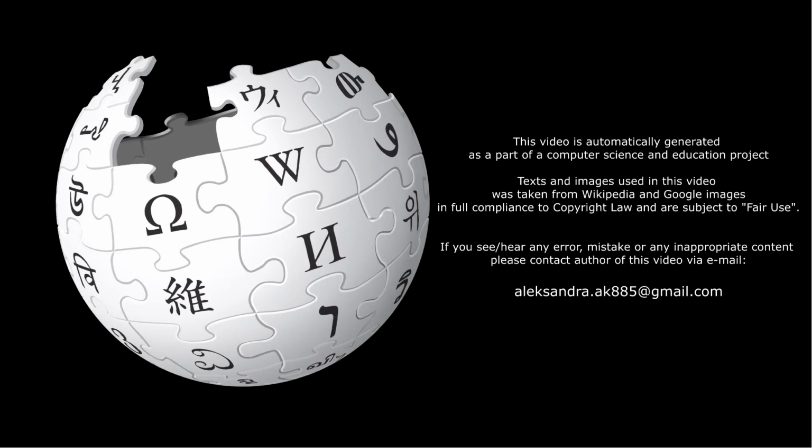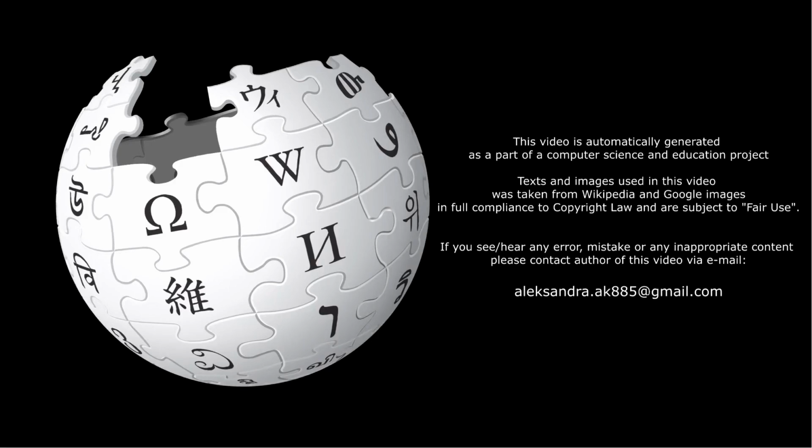Still, since diffusion of contaminants is expected to be much slower in water than in air or vacuum, consideration of optics contamination actually favors immersion lithography. Water-soaked photoresist also has been demonstrated to produce very satisfactory images. In addition, 193 nanometers light has been known to ionize water, producing solvated electrons, which may spread and react with the photoresist, affecting the resolution performance.